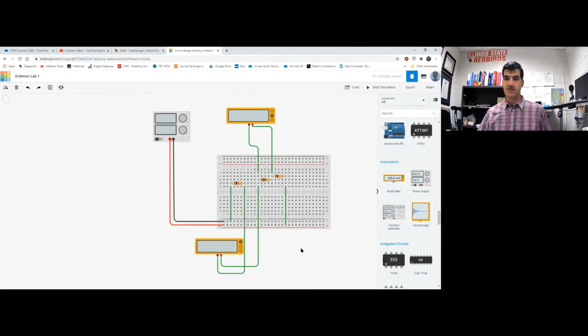Like that. All right. So now the current path is going to be through the positive side, from the positive side over to this wire, through this resistor, and then it has no choice but to go through this wire, measuring the current, and then out through this wire, where it will go through the third resistor, then through this wire, and back to the negative side. All right. So I should get the exact same thing. You know, assuming that there might be a slight rounding error, but it really should be the exact same amount of current, because this is a series circuit. It should get the exact same thing.